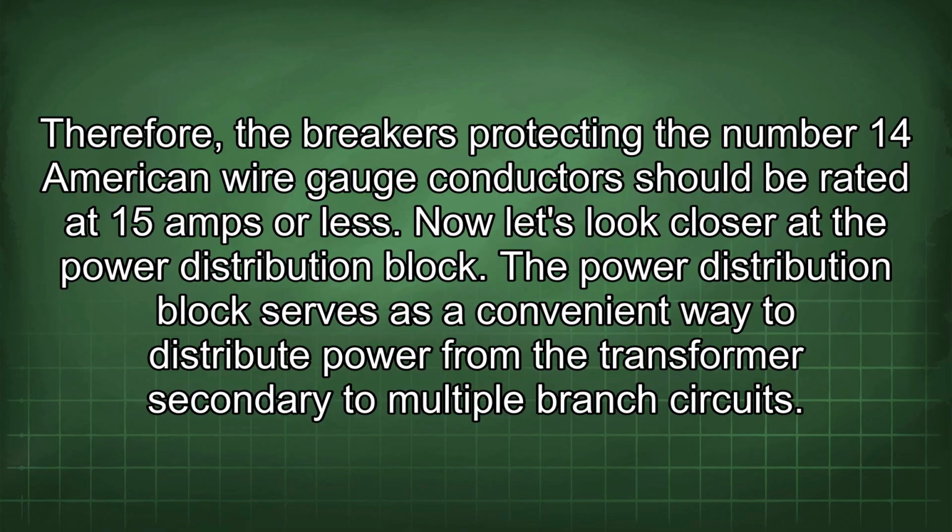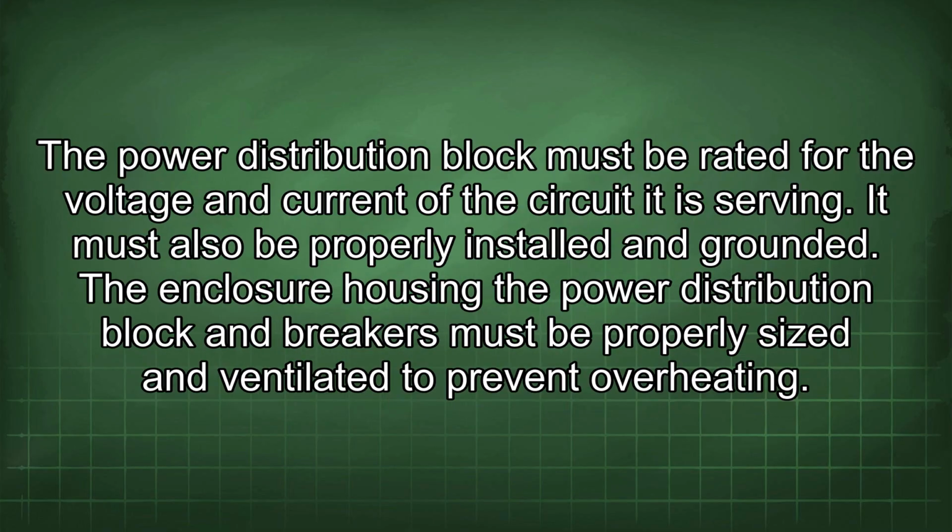Now let's look closer at the power distribution block. The power distribution block serves as a convenient way to distribute power from the transformer secondary to multiple branch circuits. The power distribution block must be rated for the voltage and current of the circuit it is serving.